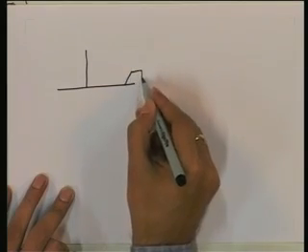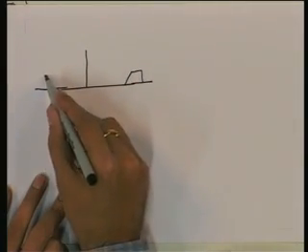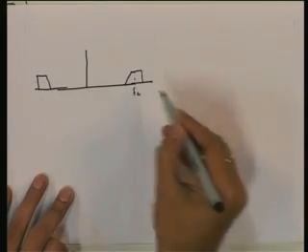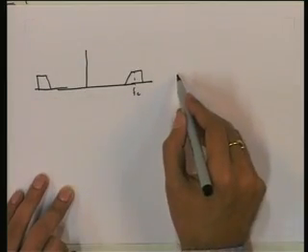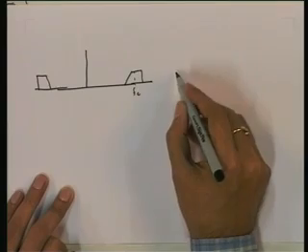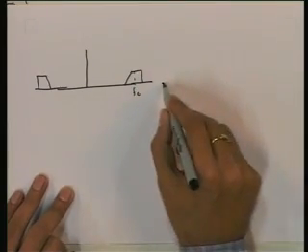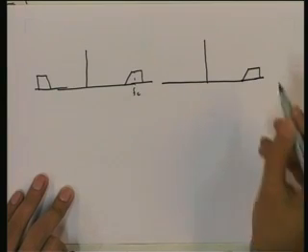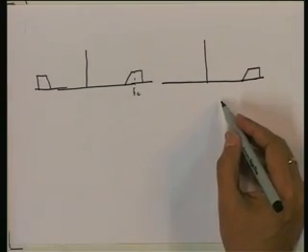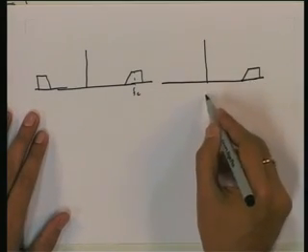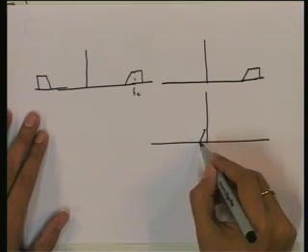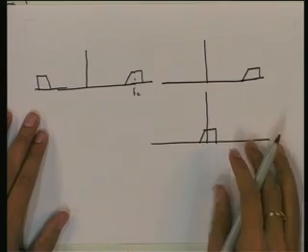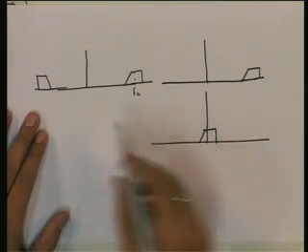If we have a bandpass signal with this kind of spectrum, this is Fc, then we can first suppress the negative side by multiplying by 2 times u of f, that is the unit step function, and then we will get again a bandpass one sided spectrum. The resulting signal will have this spectrum, negative side will have nothing. Then we can shift this spectrum here, then we will get a signal with this kind of spectrum. So, this will be a low pass signal, and this is called the low pass equivalent signal of this bandpass signal.